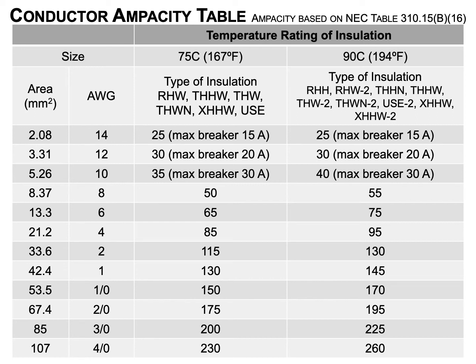The insulation will most likely be thicker on the 90C degree type, which has advantages and disadvantages. Maybe I'm trying to pull many wires through a conduit, and if that insulation is thicker, the code will tell me I can only pull so many wires through that conduit with that thicker insulation. Well, there might be an advantage to using that thicker insulation because I can run more current through that wire, and it might be less expensive in the long run instead of pulling more wires.